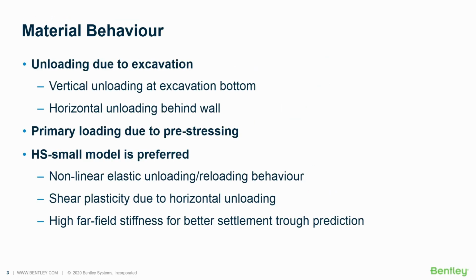I would like to say a few more words about material behavior, which is also quite important for excavation. You are dealing with an excavation problem where you will be facing both unloading and primary loading. And the unloading will be happening in vertical unloading as well as horizontal unloading behind the wall. So you clearly realize that we are having a situation here where the stress path being followed by the soil will be completely different depending on the location where the stress point is located. And for that, you need to have a constitutive model which is capable of taking this into account properly.